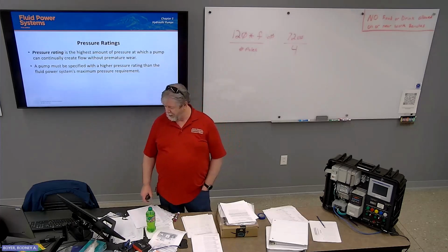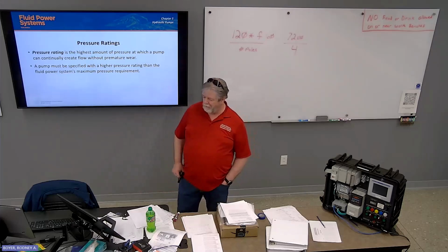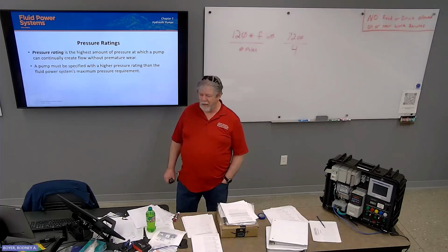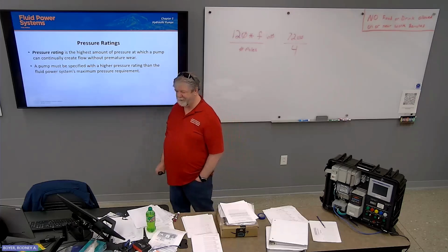Pressure rating is the highest amount of pressure at which a pump can continually create flow without premature wear. A pump must be specified with a higher pressure rating than the fluid power system's maximum pressure requirement. Why do you reckon that might be?